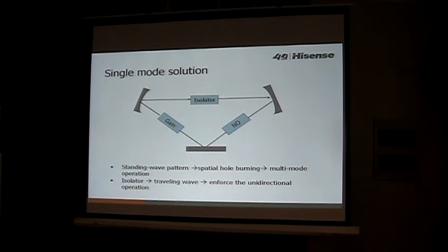So when you try to get the laser, some parts of the gain material will get consumed while other parts are left untouched. Some people say the mode competition in a laser is a kind of winner-take-all. But if you have this so-called spatial hole burning, then some region of the gain medium will not be consumed, still leaving room for other modes to get excited.